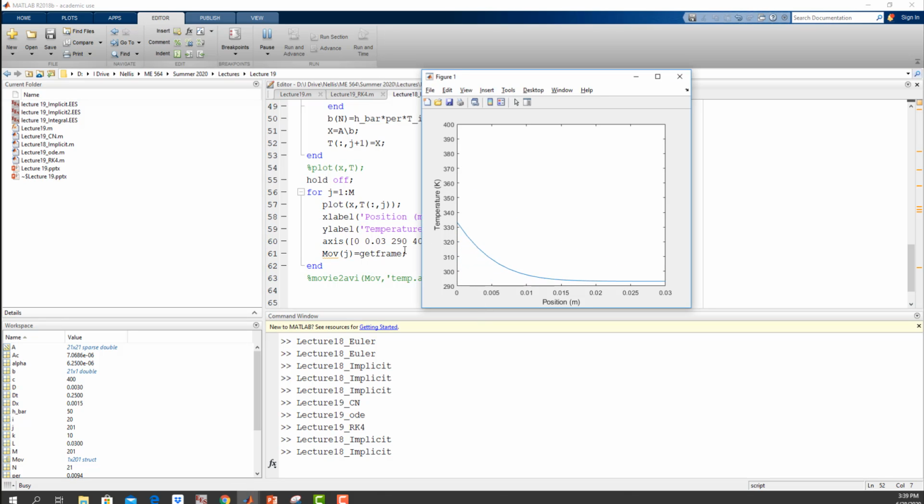So it starts at T infinity, and then you can see, this slope here is always the same because I have a constant heat transfer rate. The tip is adiabatic, and then you can watch this thing evolve. And actually, this is a good place to stop for a second and think about what's going on physically and how much of this solution we could have anticipated before we even started working on a numerical model.